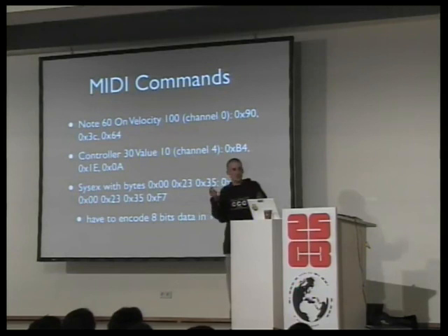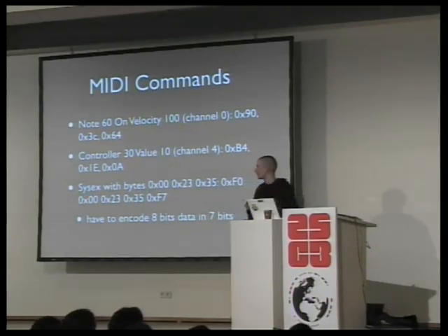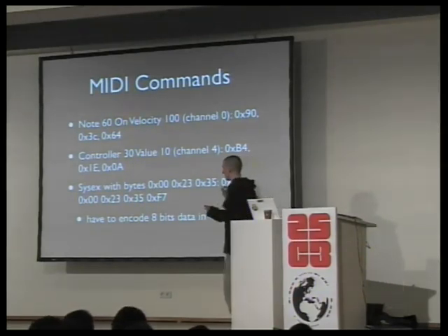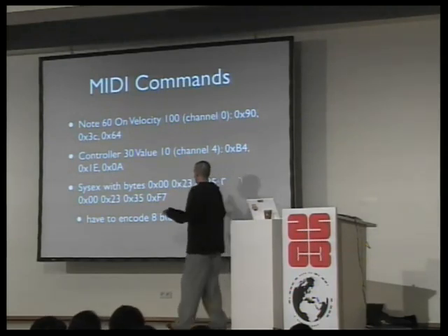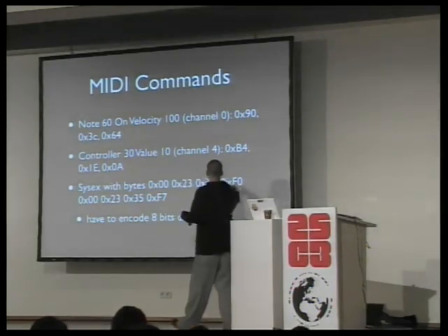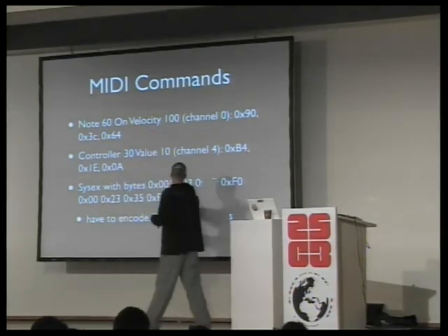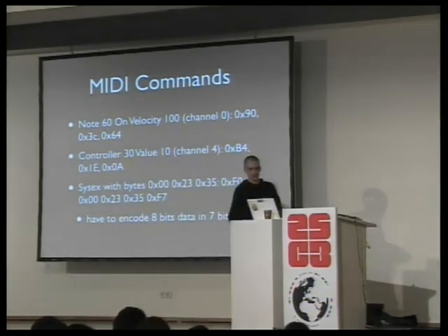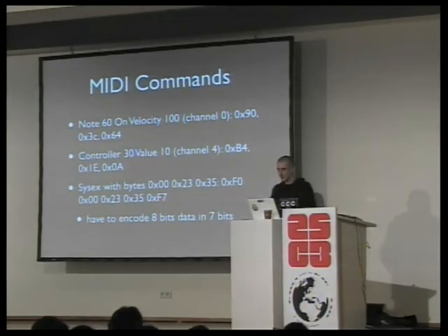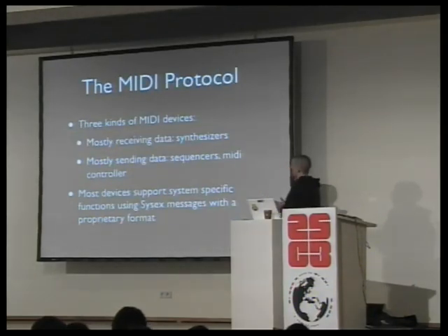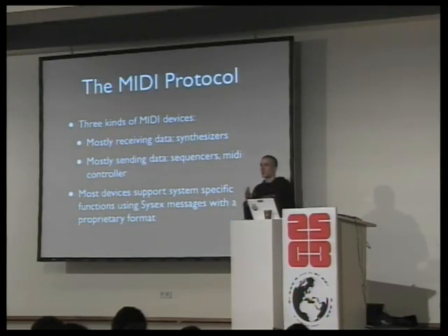Okay, yeah, there's some way to actually put the length in it, but I think it's just the first byte which is specific, which says, you know, this is the start of a sysex message, that's the vendor ID, and that's the end of a sysex message, and what's in between is actually whatever you want. So on the MIDI side, that was what the protocol looks like.